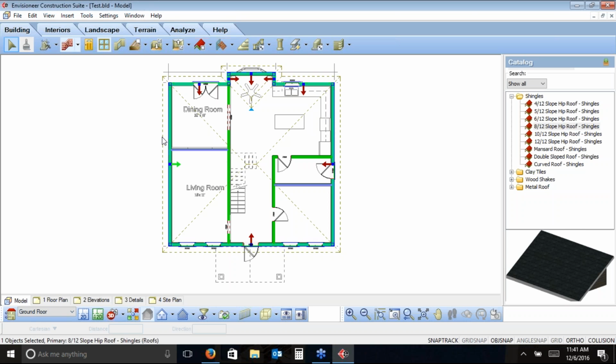I'm just going to left click on one edge of the roof, and when I do so, it's just like the ceilings. You'll see those individual arrows. Those individual arrows are all part of the individual sides of this roof. They're all pointing to those individual sides that it sees. The green arrow means I've picked on this one side, and if I pick on an arrow, I can change it to green as well. So what I do to the one side, I'm also doing to the other at the same time.